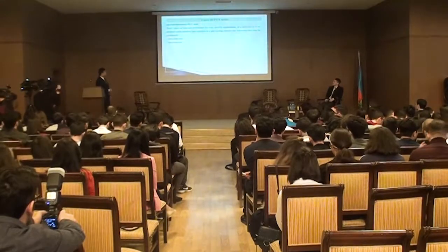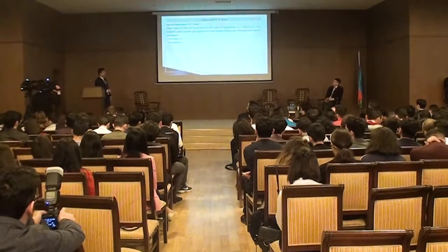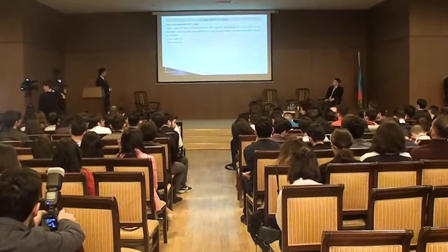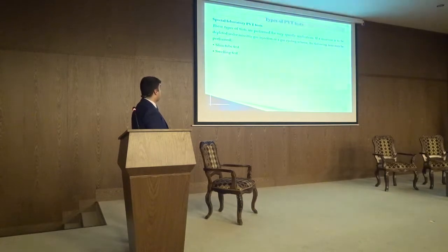And another, specific type of PVT test is slim tube tests and swelling tests, and both of them we use to define minimum miscibility pressure and minimum miscibility concentration. First one, we will define minimum miscibility pressure and minimum miscibility concentration.